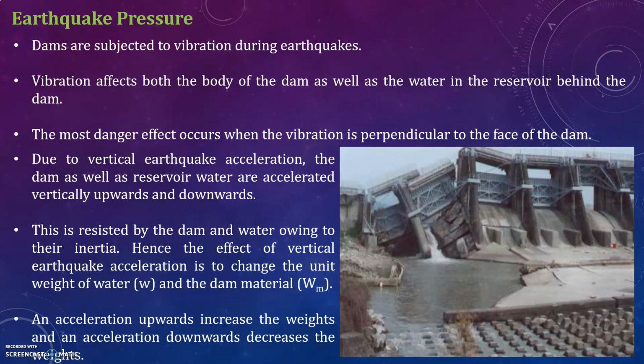The waves impart accelerations to the foundation under the dam and cause its movement. In order to avoid rupture, the dam must also move along with it. This acceleration introduces an inertia force in the body of the dam and sets up stresses initially in lower layers and gradually in the whole body of the dam.